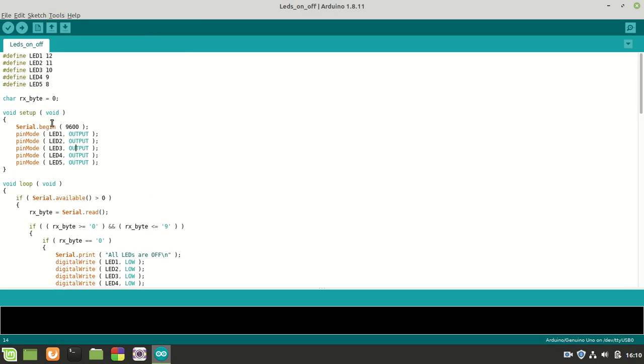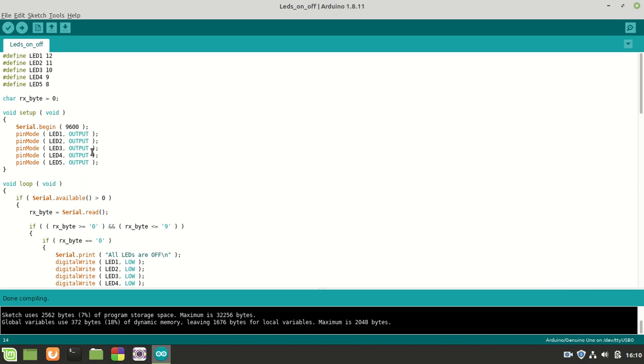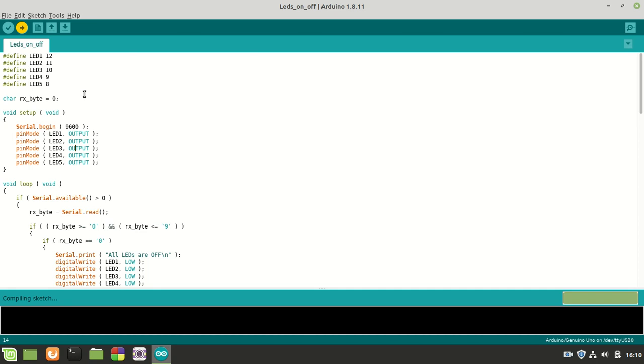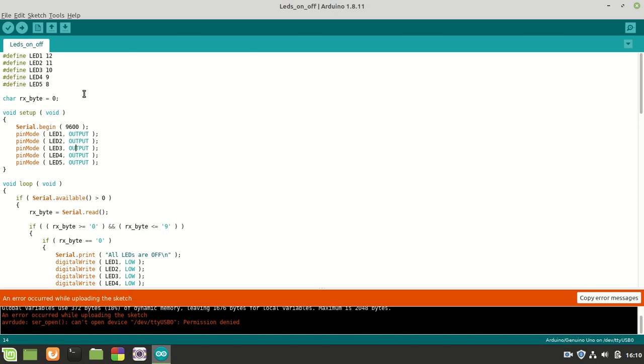Like me, I have something right now, and I'm going to verify it. So this means I'm going to compile this sketch and see if we have some errors. As you can see, we have no errors, which is good. And now we are going to upload it to our Uno board, and as you can see we have a problem. It says avrdude cannot open the device /dev/ttyUSB0 because we have no permission.